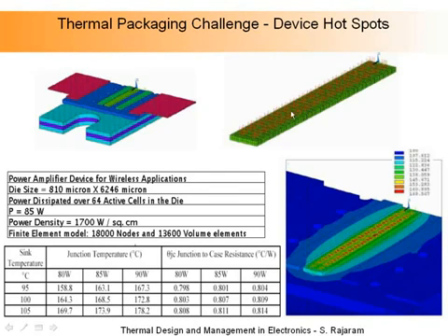Now, each one of those may be dissipating a small amount, but the total power from all of these being dissipated is 85 watts. If I looked at the area or the density of heat on this, based on the size of the die, the power density is 1,700 watts per centimeter squared. So just imagine that. It's like putting a toaster oven on top of this small surface. This is the high heat density that we are dealing with today inside those devices.